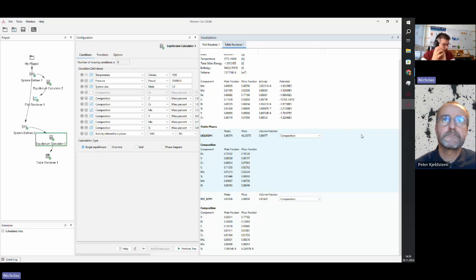And again, this is the important thing: do you achieve thermodynamic equilibrium? I would be very surprised if you achieve the thermodynamic equilibrium content of nitrogen in the liquid steel if it's in contact with an atmosphere, right? Because there are things that I know from electric arc furnaces and from ladle furnaces, about how much nitrogen actually goes into the steel.